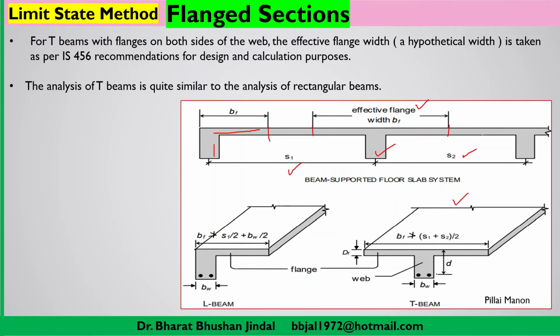I already told you that this portion is the web and this is the flange. So this slab, if you cut from here, is considered as the flange of this T-beam. And from this topmost fiber, as we have taken in any singly reinforced section, if this is steel, then this distance we consider as effective depth. That means the distance from the top of the flange to the center of the reinforcement in the web portion will be the effective depth of this T-beam section.